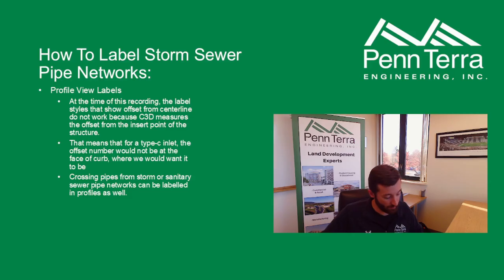Okay, next up, how to label storm sewer pipe networks. Okay, so a note, and I know we've talked about this before, but it's worth mentioning again. Currently, the label styles that show an offset from the center line, we do not want to use. These would be inlet labels, because Civil 3D measures the offset from the insert point of whatever structure you have.